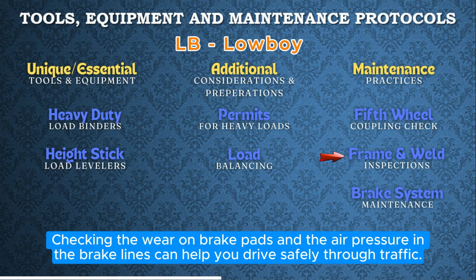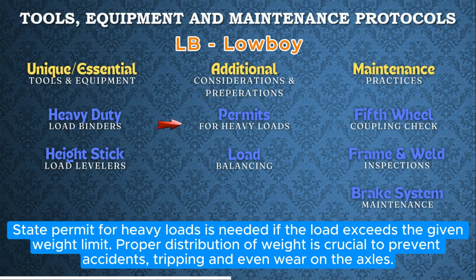Checking the wear on brake pads and the air pressure in the brake lines can help you drive safely through traffic. State permit for heavy loads is needed if the load exceeds the given weight limit. Proper distribution of weight is crucial to prevent accidents, tripping, and uneven wear on the axles.